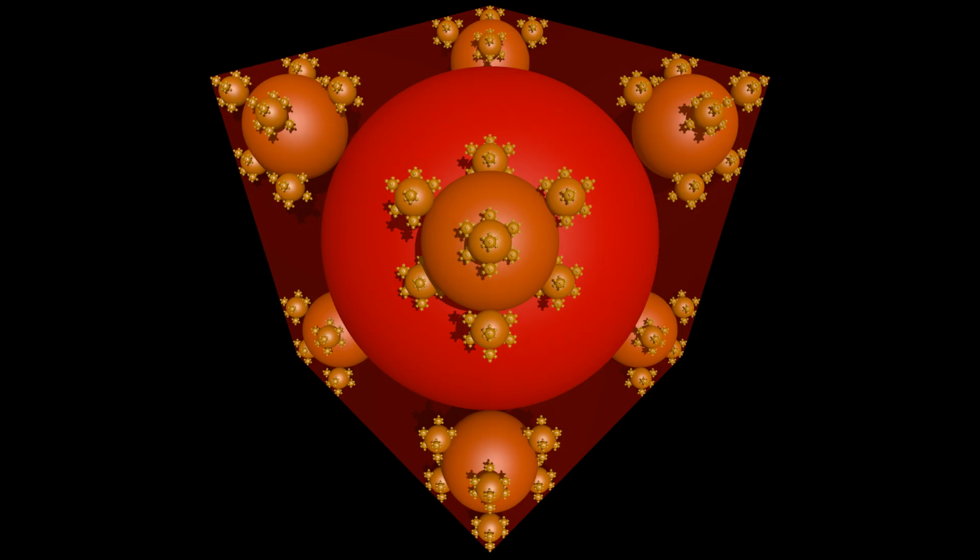With this information finally obtained, we can set up our inner loop. For each large sphere from a previous loop, we define 8 smaller spheres scaled by the ratio just defined. These spheres are first located in an equatorial position, touching the large sphere, and then rotated around the z-axis by either minus or plus alpha. Finally, they are rotated around the y-axis for obtaining their final positions. After this inner loop is finished, the outer loop redefines the smaller spheres as the new larger spheres, and the inner loop starts for all new positions again.